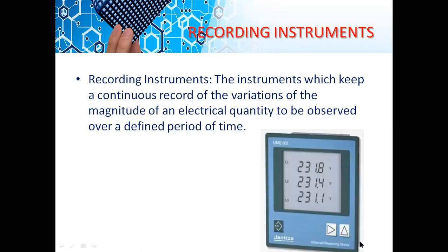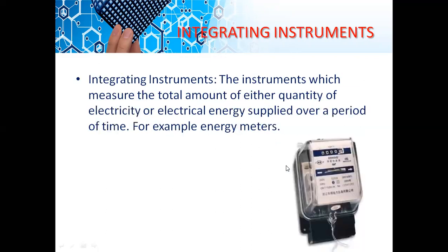And then we have seen recording instrument. Here we have a digital or an electronic instrument with a digital display. This will have track of the data. So we use it for recording purpose, for monitoring purpose especially, we use recording instruments. And then integrating instruments. Best example of integrating instruments is energy meter. Energy meter is going to integrate power with time.